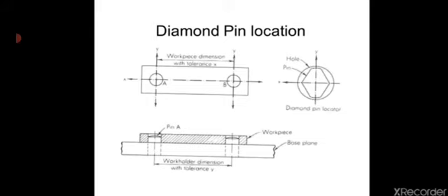Here a workpiece is shown located on pin P, and for accurate location there is a small clearance between the pin and the hole. After correct location on this pin, the workpiece can rotate in either direction about the pin. Hence, due to the clearance between pins and holes, the center distance between two holes and two pins does not remain fixed.